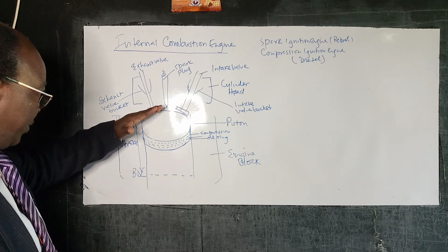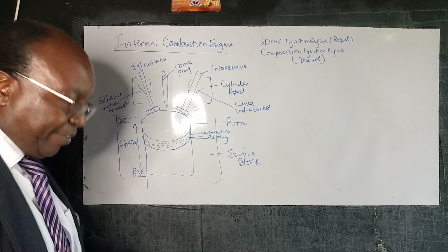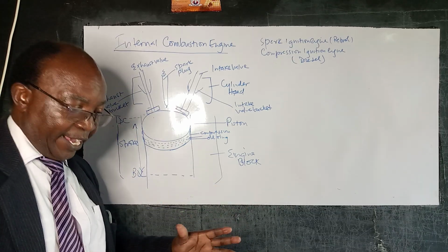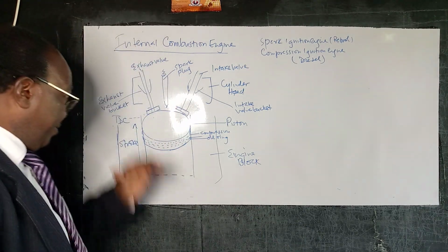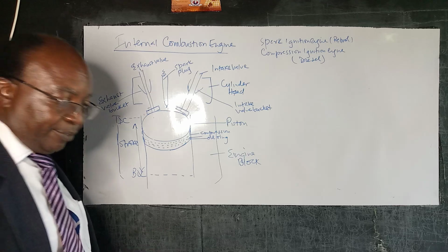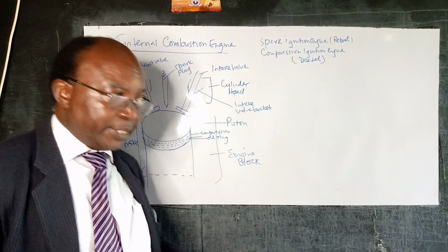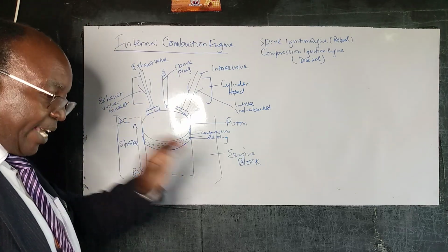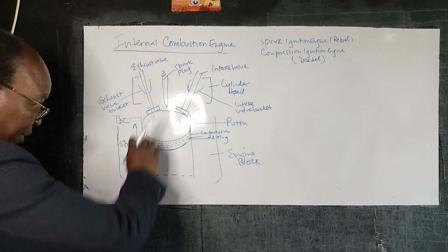So these valves are always supposed to sit on a valve seat, which they should fit perfectly. In case the engine is aged and has been rebuilt, they will actually have to grind the valves using a paste grinder, which has both coarse and smooth fine ends. They grind those so that the valves lie properly on the seating.